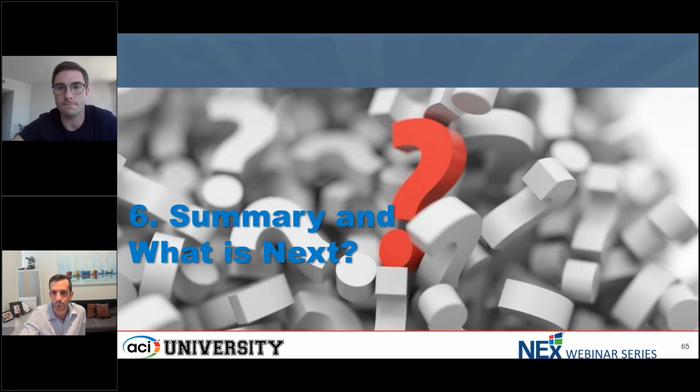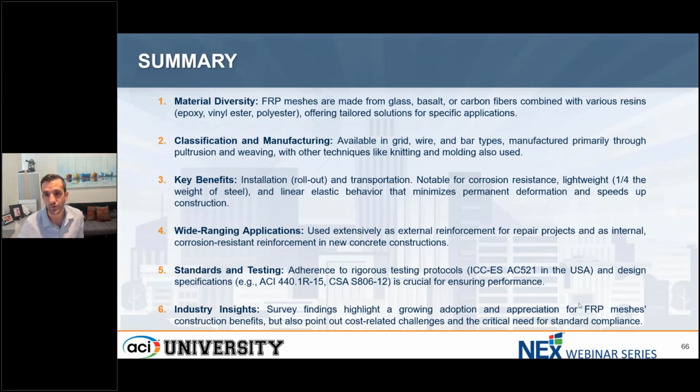Thank you, Dr. Rees. Let's summarize what we've learned so far in the last hour, without going into the detail of the specific ones, as you can read on your slides. I think we are seeing that FRP meshes are enabling concrete construction, primarily through the reduction of labor costs, which increases the speed of construction and productivity. We do have test standards and design methods, as well as design aids, which are helping advance the industry.